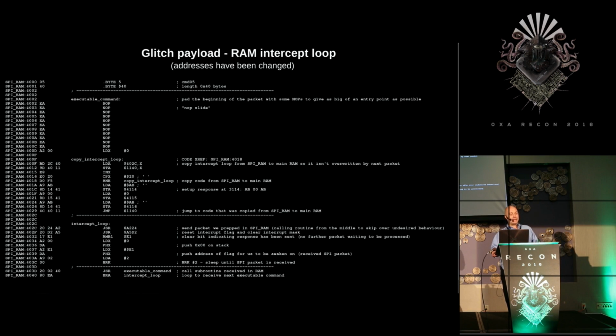So I decided to take a chance and test if the RAM was executable. I send a message via SPI. I know that this is going to be stored in RAM. This message contains 6502 executable code that will copy itself to an unused area of RAM, execute from this area, and send an ACK indicating it was successful. Because I've already studied the use of the SPI interface, I was able to create this executable payload that will continue to receive commands via SPI after it's taken control of the ACP.